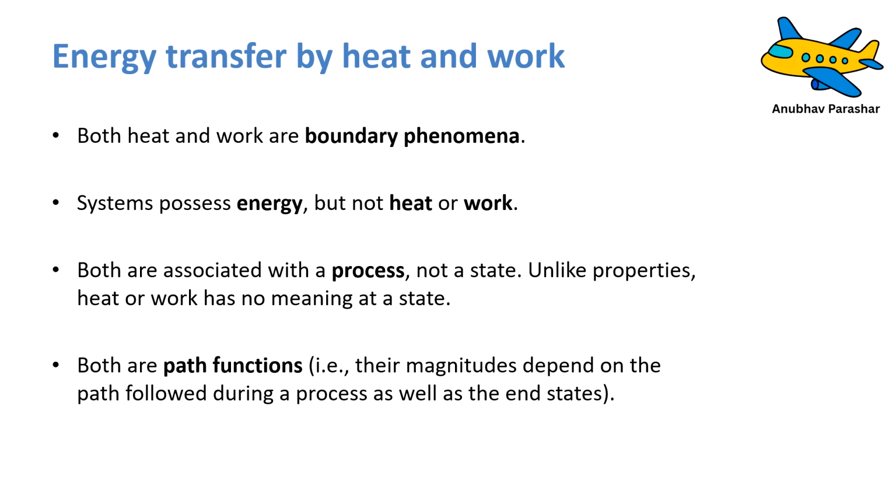So let us summarize the energy transfer by heat and work. Both heat and work are boundary phenomena, right? Whenever the energy crosses the boundary, we say heat and work are defined only when the energy crosses a boundary. Anything which is happening within the system will not be considered as either heat or work. We saw that example in the burning candle case, right?